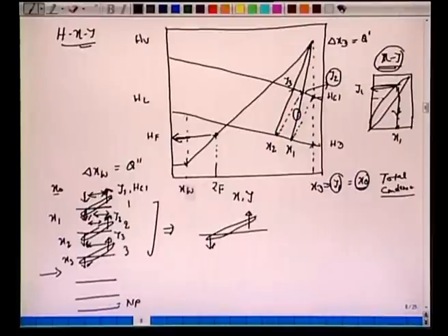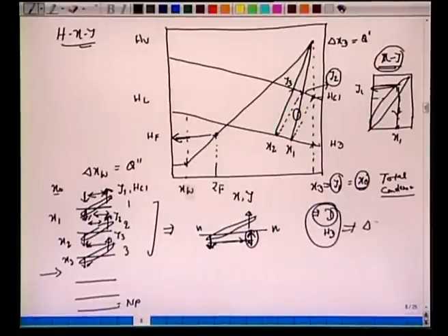But the molar flow rate of the vapor which arrives and the molar flow rate of the liquid which leaves, the difference is always a constant, given as top product which we have as T. Similarly, the enthalpy difference between the vapor which arrives at any plate N and the liquid which leaves that plate N has the same difference given as HT. So that's what corresponded to this difference point, delta XD or Q dash.